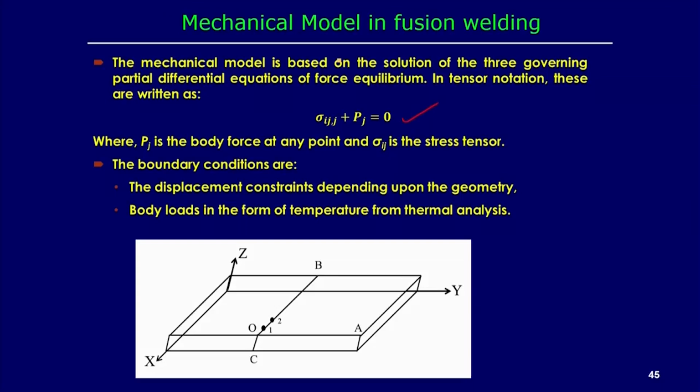So, of course, when we use this governing equation, that means the force equilibrium equation, along with that we also need some boundary conditions. In terms of the displacement constraint, we generally put the boundary condition depending on the geometry, and the body force in the form of the temperature. So, the displacement constraint is in terms of the boundary conditions, and at the same time the body force can be called the load to the thermomechanical model, which can be estimated from the temperature distribution.